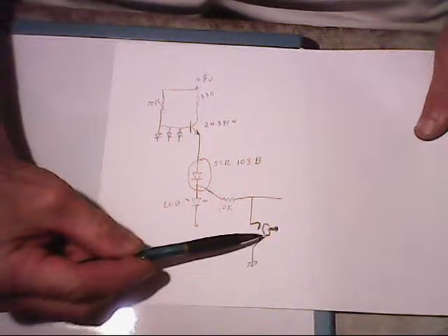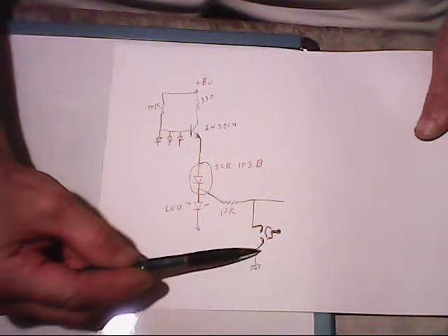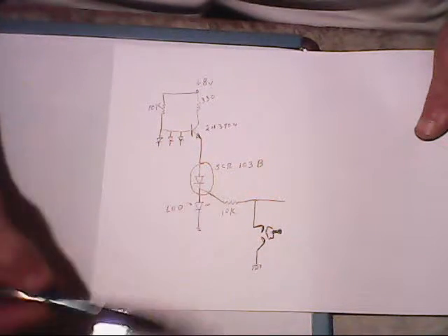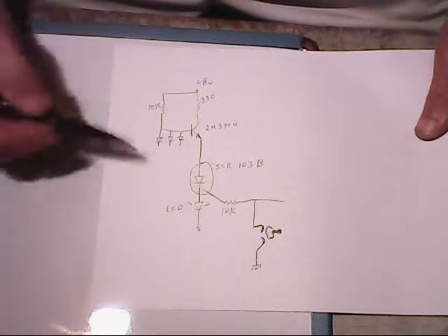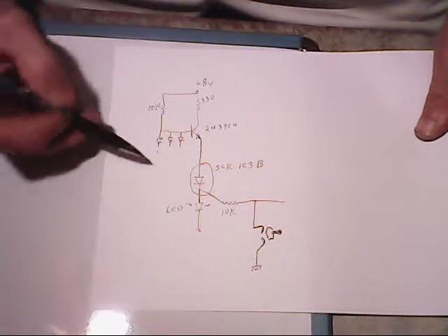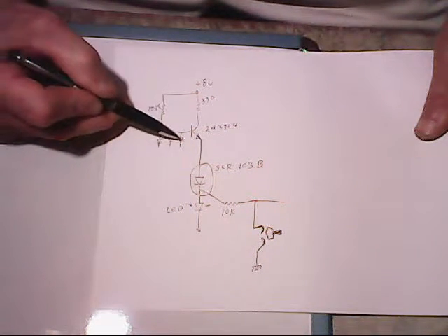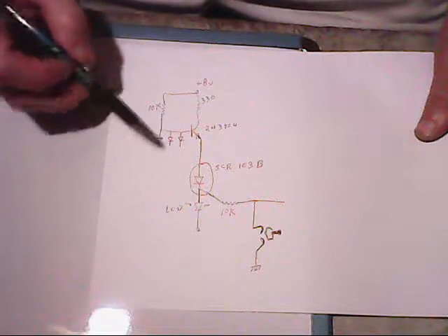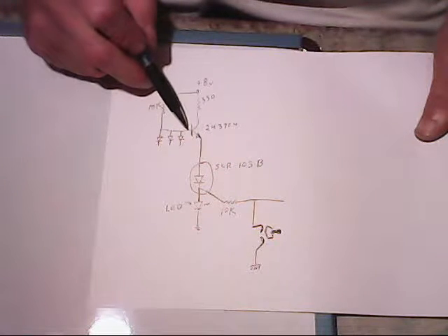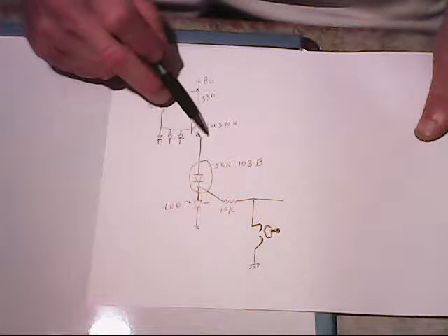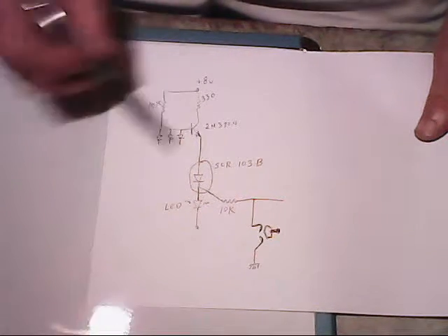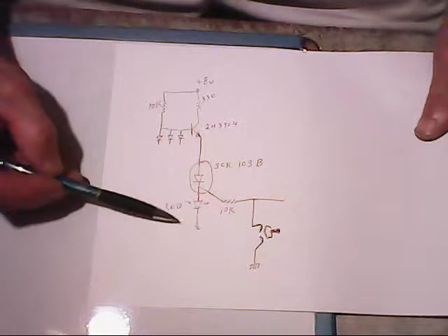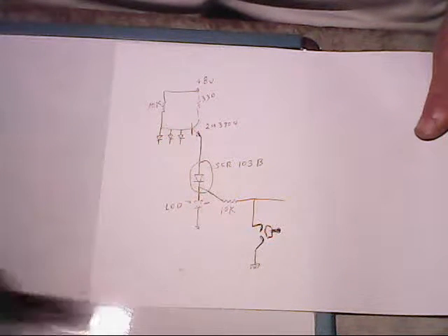When we apply a positive voltage to the gate of the SCR, then the LED should light up. If we put a negative pulse to any one of these diodes here, these 1N914s, that will bring the base down low and cause the NPN transistor to turn off, which would then shut down the SCR, and then the load would go low again, and it'd be ready for another input again.